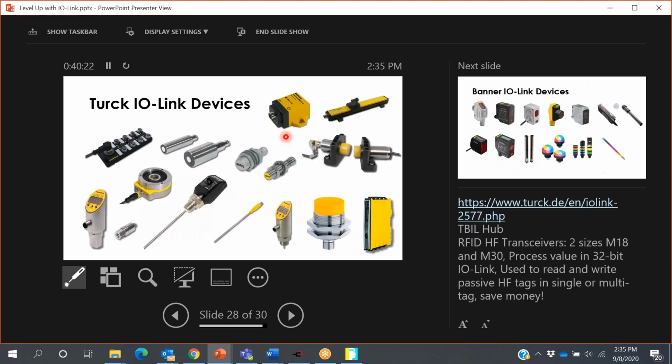So that's the master side of it. We have different pressure sensors, temperature sensors, talked about the encoder a little bit. That's this device down here. It's not connected, but it uses an inductive target, and you can handle about 5 to 7 millimeters of separation, so it's non-contact, and it just measures 0 to 360 in an absolute way, so you know exactly where you are in that one revolution.